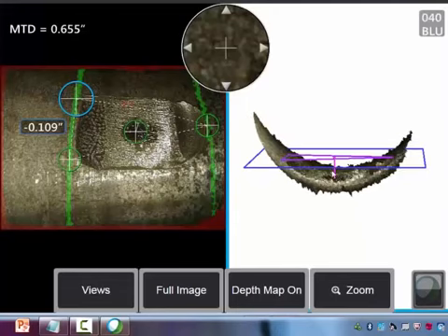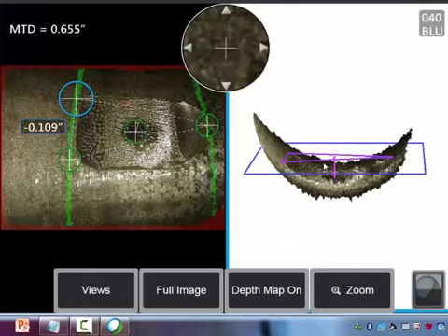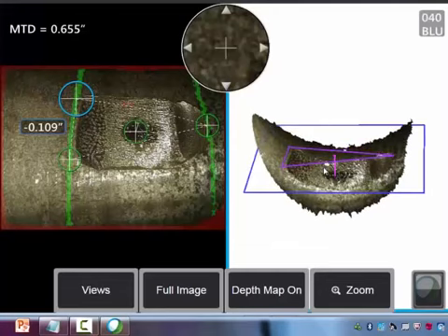And this depth measurement that we're making is really measuring this curvature much more than it's measuring the depth of this indication. So we can tell clearly that this is not going to be an accurate measurement. So the first common mistake that's easy to avoid using the point cloud is misinterpretation of the shape of the surface.